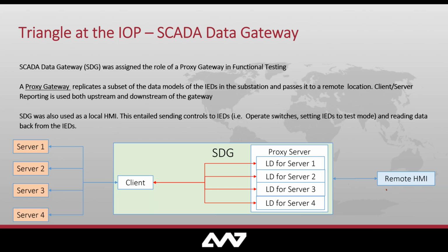So because we're doing 61850 all the way through, and because we're preserving the data model of the device, we're really saving that structure. And in some ways, it's almost transparent to the remote HMI. He does know that he's only talking to one server, but he sees the different logical devices that represent all of the different IEDs in the substation. Christoph, do you have anything you'd want to add?